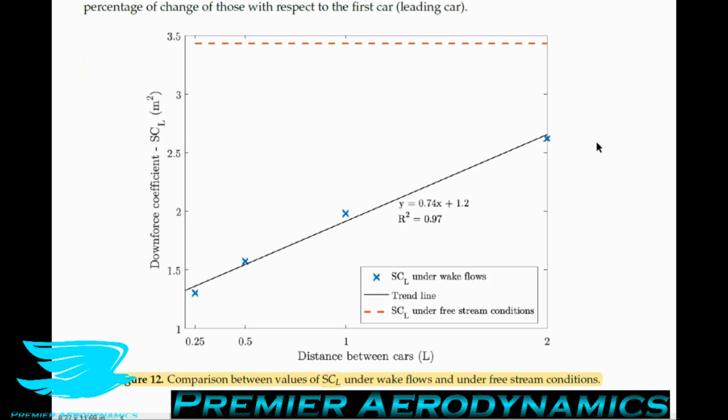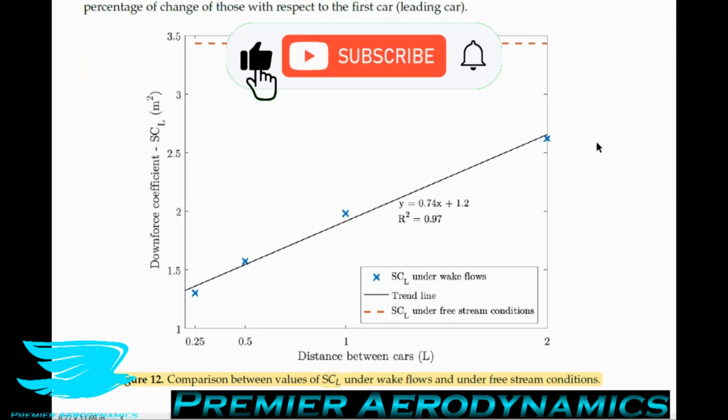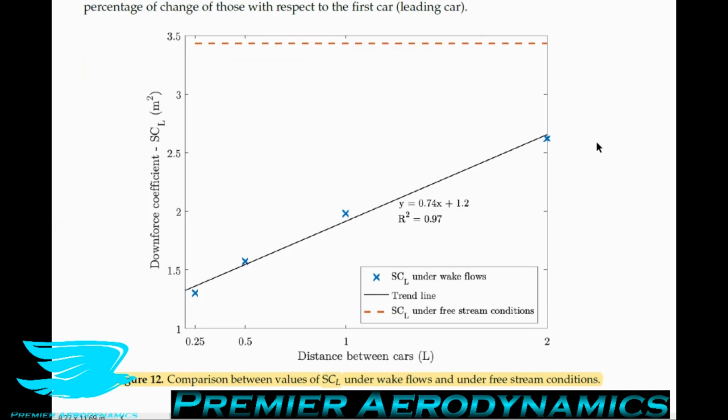So in other words, the amount of lift that the car is producing when it is closer to the upstream vehicle and downstream of it, compared to the free stream condition. In the free stream condition, the lift area being produced is about 3.45, so it's quite high. But when we are under a wake flow, so in other words, there's a wake from the upstream car hitting the downstream car, the downstream car is now producing much less lift. So let's talk about that.